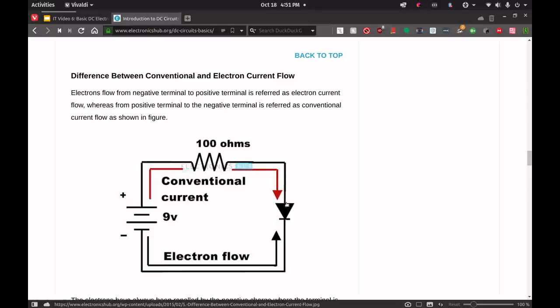That's why you'll see diodes having an arrow pointing in the direction of current flow. Technically it's wrong, but it doesn't matter. It actually does not affect anything when you're looking at circuits. I only mention this because if you're looking at a technical diagram for electronics technicians and it talks about electron flow, especially if it has a directional arrow like this, say through different pathways, it'll be coming from the negative side of the battery or the power supply through the circuit.